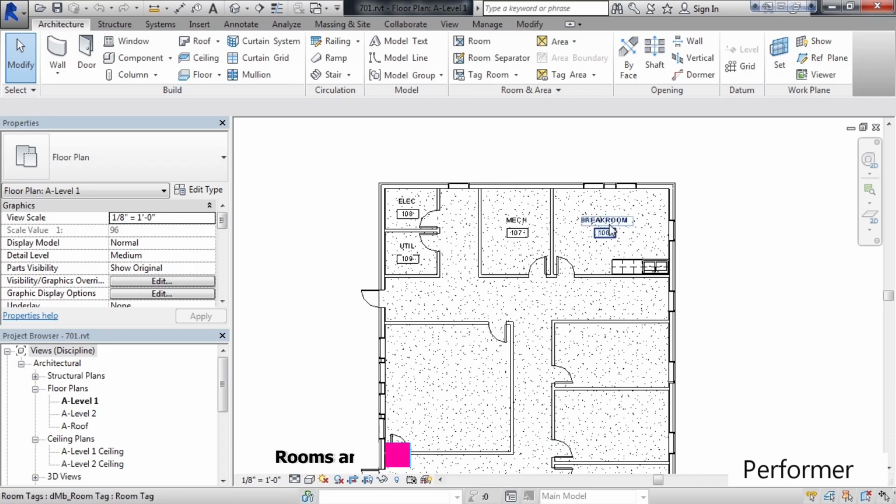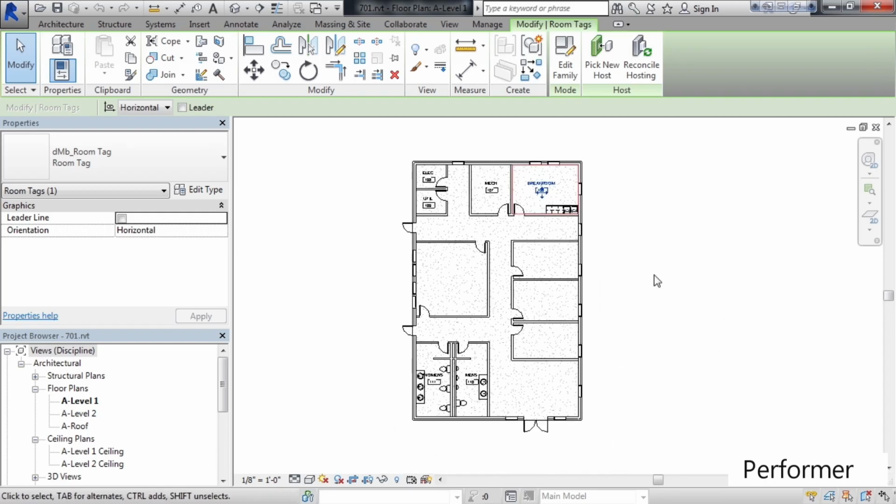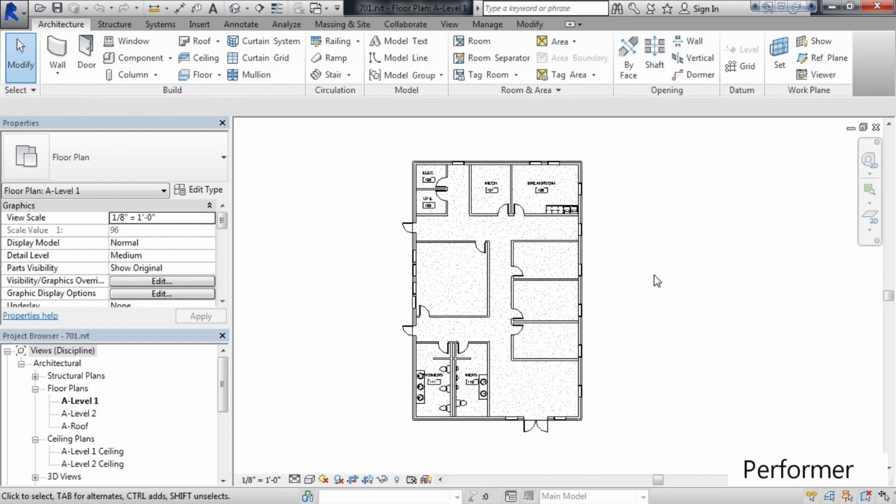And if I move over the room tag, I actually see it highlights, and it does say room tag. And if I move my mouse a little bit again, I actually will see the actual room itself. Now, the room and the room tag actually can be placed individually or placed together. The rooms can be added before the tag names and room tags, or you can add the rooms to a room schedule and then place those rooms that are already predefined.